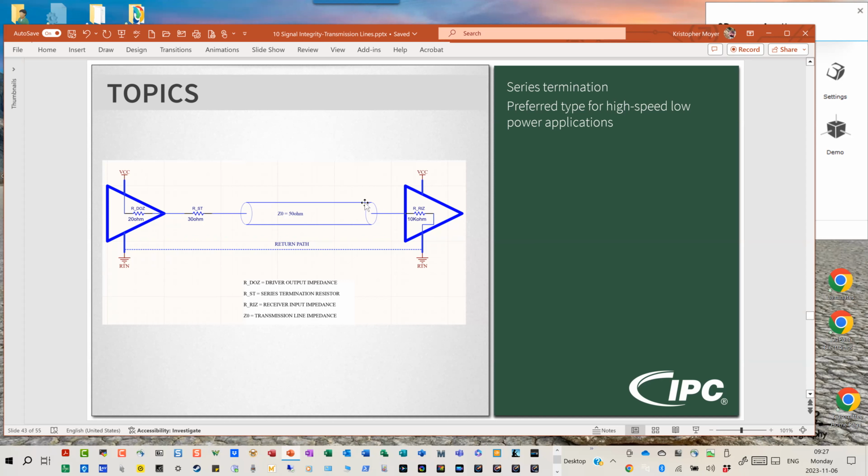What is actually doing that pushing and flowing is an electromagnetic wave. But due to the complexities of Maxwell's equations and true 3D field solvers, we teach the simplified distributed methodology of voltage pushes, current flows as distinct entities. And it works. Don't get me wrong, it is a fine method. But to understand what's really going on in our circuit boards, we have to consider these as three-dimensional electromagnetic waveform structures, and therefore start thinking of them in terms of Maxwellian equations, 3D field structures.